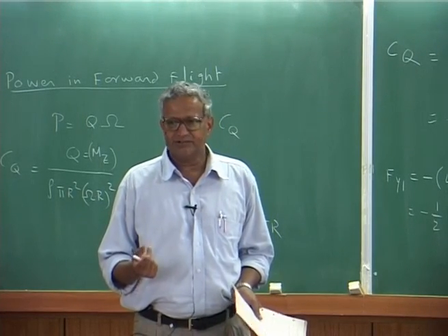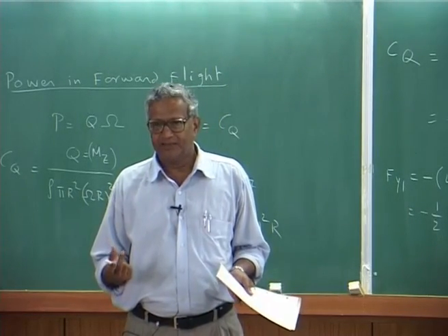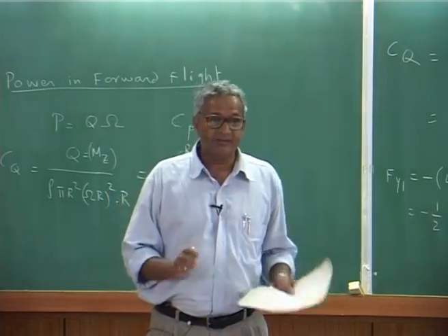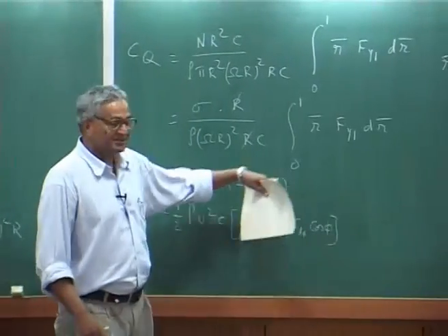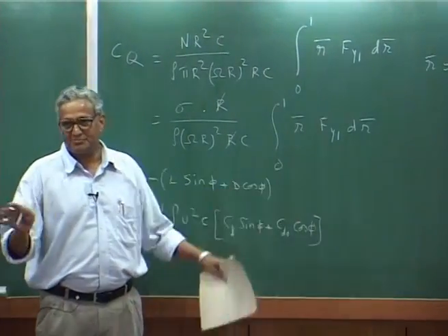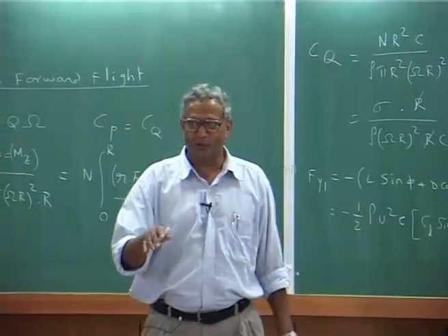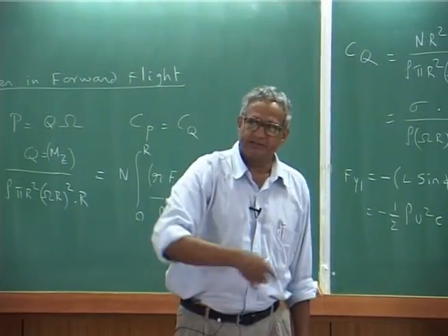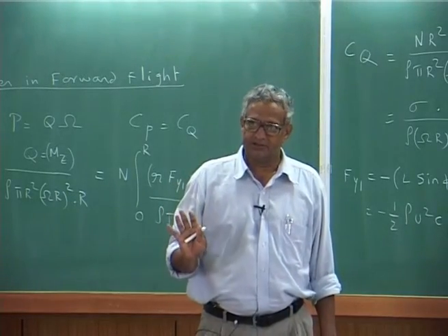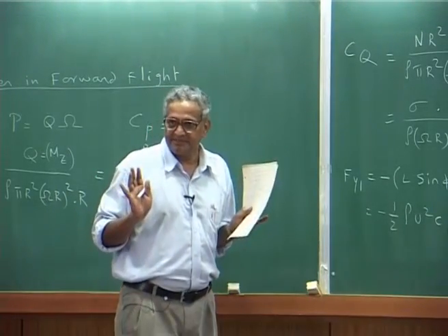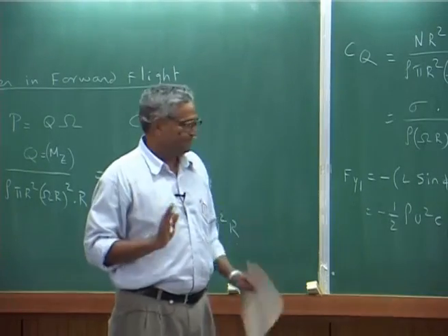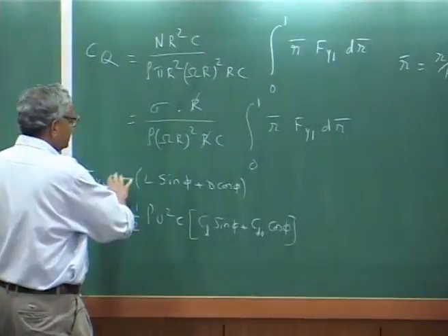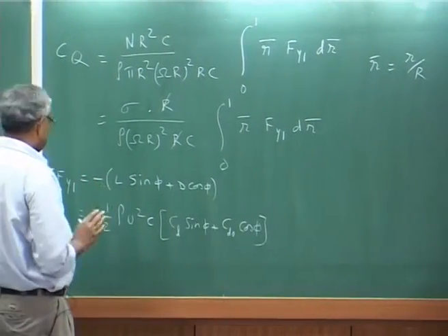Okay. So, since we are calculating power, it does not matter, the sign we will throw away. So, we will not be carrying on this sign completely, sign does not matter, it is only to say that this is the quantity, because if the rotor is rotating counterclockwise, my torque is clockwise, that is all. So, I am getting the torque coefficient as a magnitude, because that is basically the power coefficient. So, the minus sign we are throwing out.